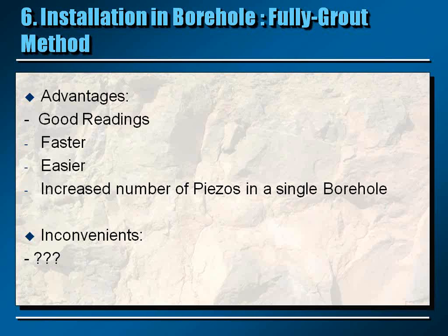This method, up to now, seems to give good readings. It's much faster, and the installation is much easier. And you can install more piezometers in a single borehole. The inconveniences up to now are not so clear. This method is quite new. We don't have a lot of feedback from this method, but all the feedback we get is positive. But still, there are some doubts.